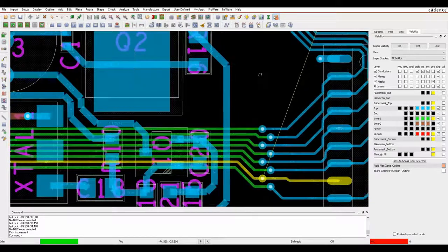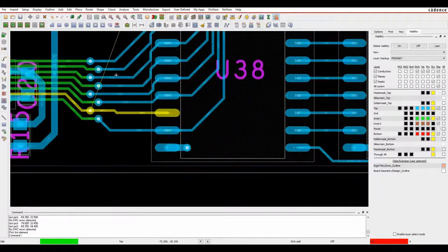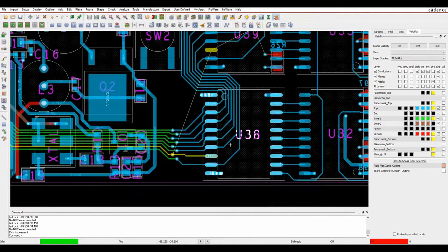When I've completed the routing, you can see things like the embedded net names again. So in this next example, I've got a bus here. I've already routed some items and maybe I've made an ECO or I've just forgotten to route this object. So I need to use standard things like push, shove and hug. We'll invoke the add connect command again. We'll start to route, and you can see me pushing this track. It will push the track out of the way to create the space that I need when I'm routing.